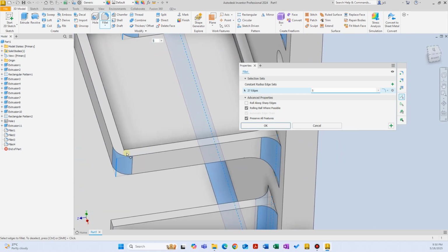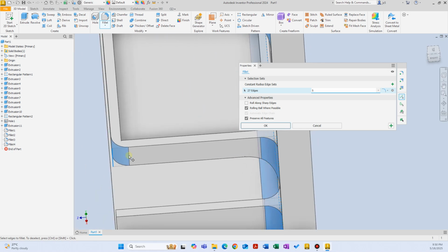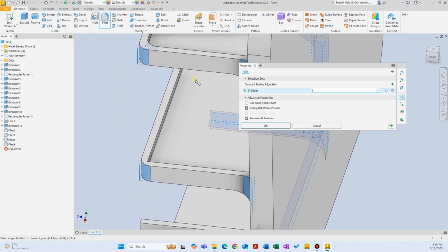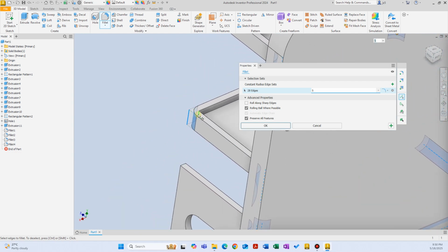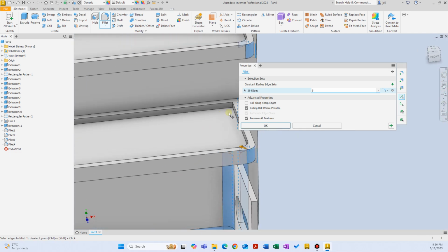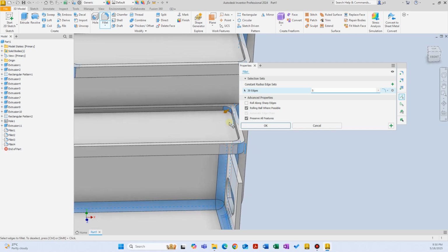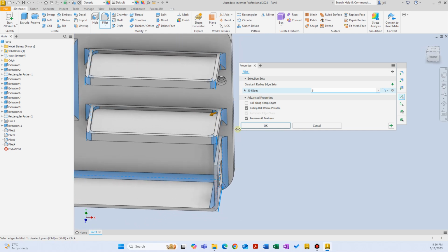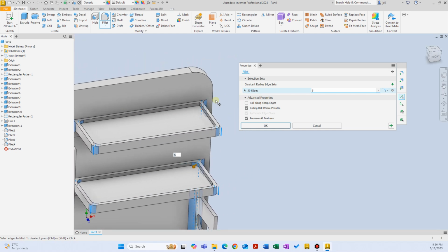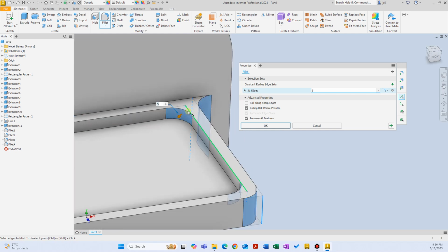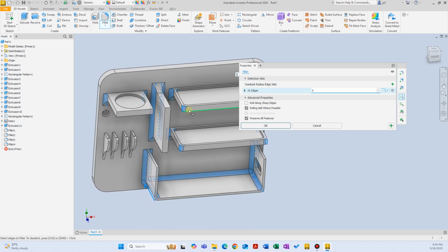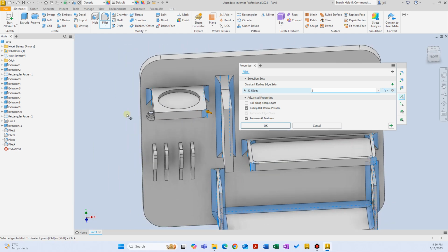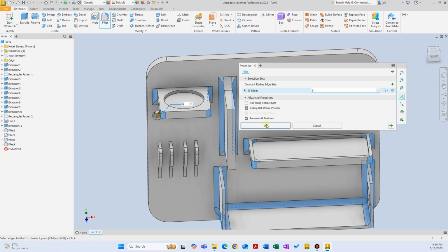See, when I applied the fillet on the outside, it removed the material, so now it's getting close to that internal corner. I don't want that, so I'm going to implement the same thing. Again, there are so many different and much easier ways to do this, but it's okay to click more than enough right now. We're trying to overuse the features and do more exercise, and it's good practice. So let's just apply 5 here, and click OK.